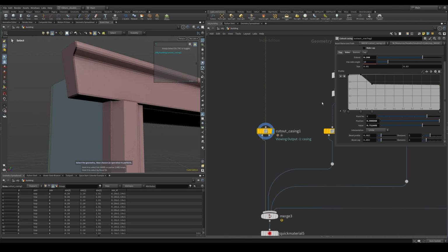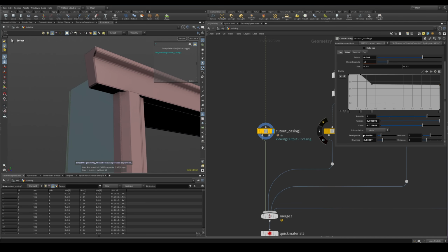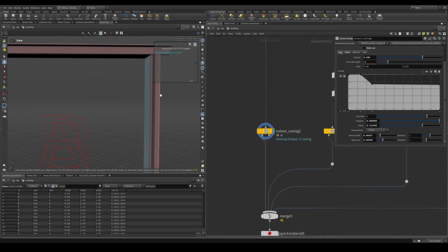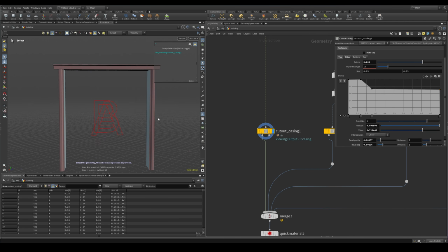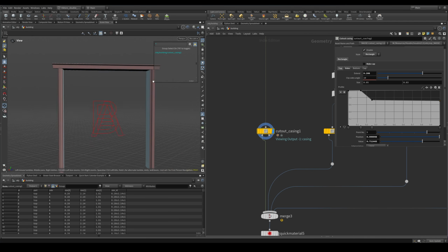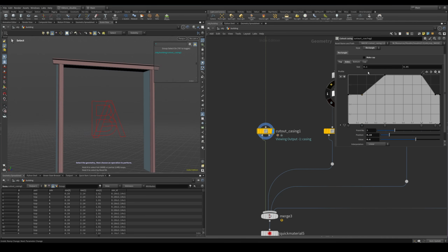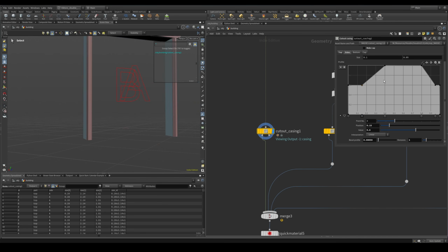And then at the end you have bevel options. The beveling is important because you may want to make it a little bit softer. So you can bevel the actual profile, which means this curve is being beveled, and then the beveling of the caps, like this. And the same options are available for all the parts of the rectangle style. So this is considered a rectangle style. You can go to the sides, again, change the profile, the sizes, and the bevels. So that's not very exciting.